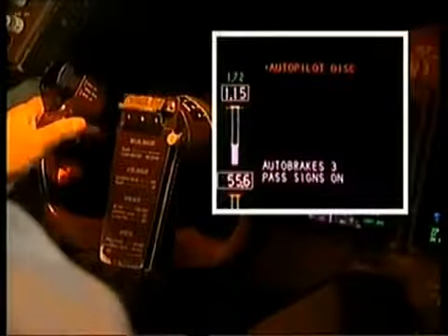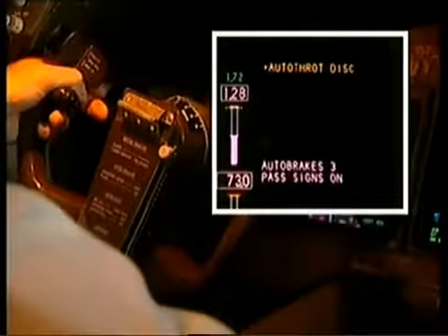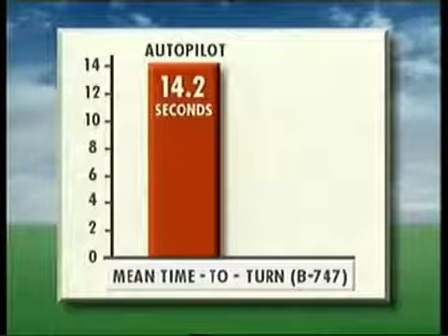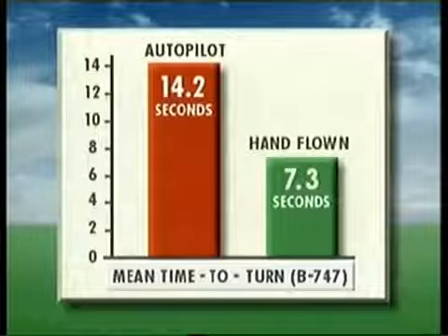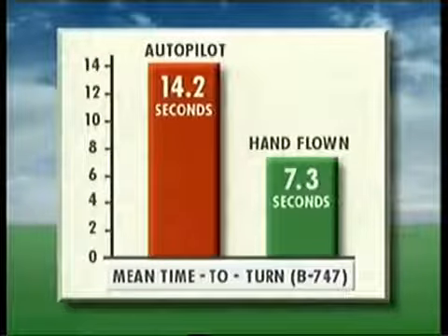While for most operations the autopilot will be used during the approach and auto-coupling is recommended to minimize deviations, for a breakout alert maneuver, hand flying is the fastest option. Simulation studies have shown that pilots consistently initiate the breakout maneuver in less time when disconnecting the autopilot and hand flying the aircraft than when using the autopilot.